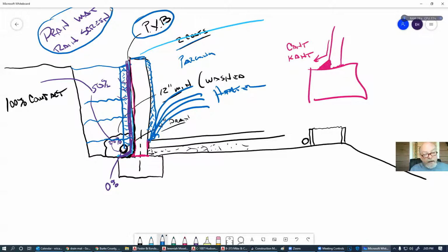The only other thing you could possibly do is, like I said in that other house, add yourself a French drain to get rid of some of this rainwater up here so that it does not become a problem down here. Any questions on any of that? Good.